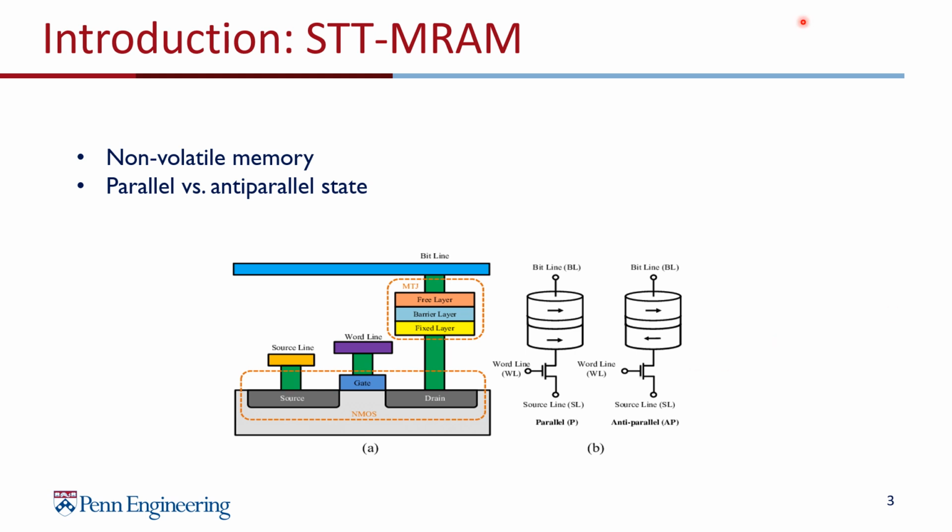In order to set the magnetic tunnel junction to the parallel state, electrons flow through the fixed layer first, setting their spin orientation to the orientation of the fixed layer, and then they flow to the free layer, setting the orientation of the free layer's polarization to be aligned with the fixed layer. In order to set the magnetic tunnel junction to the anti-parallel state, electrons flow through the free layer first, resetting the orientation of the free layer to be unaligned with the fixed layer.